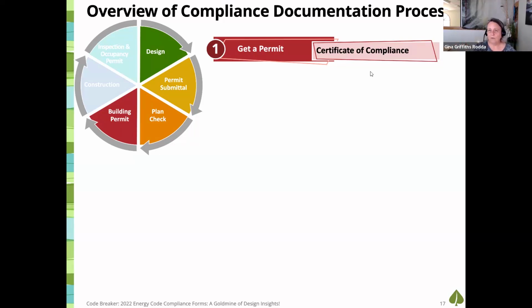And no one should have to read this certificate of compliance except for you, the design architect, to make sure what's being promised in that form is true. And you have it fully documented within that design document. You have a detail that explains and shows the insulation R values. You have a window schedule that supports the specific window specification needed. Your design has to complement the certificate of compliance. The certificate of compliance is not to take the place of your design. It's meant to support it.